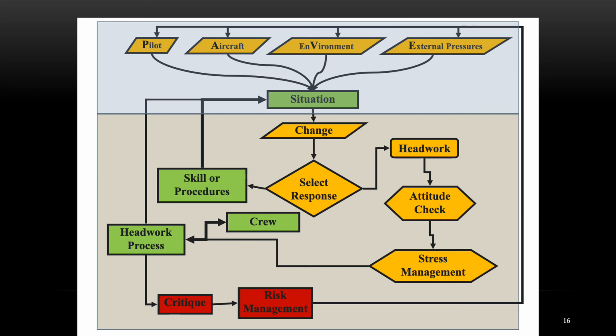Maybe you had a flight where you were landing at near your crosswind maximum, your personal minimums, and had a scary situation where maybe you almost ran off the runway or bounced really bad, and you decide that you want to change your personal minimums to avoid that in the future. That's an example of risk management.